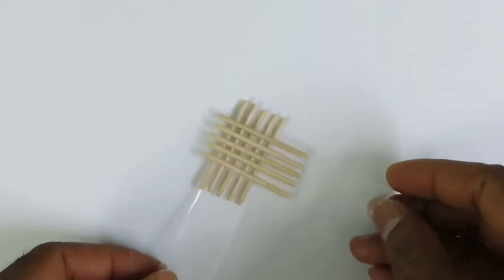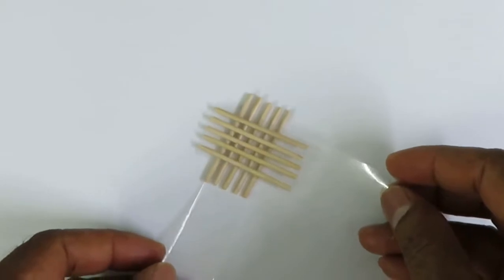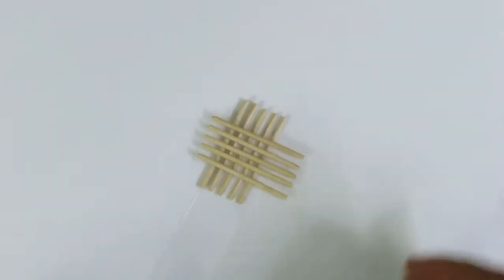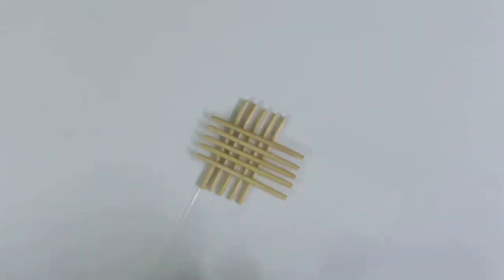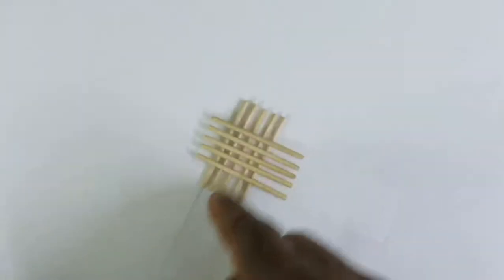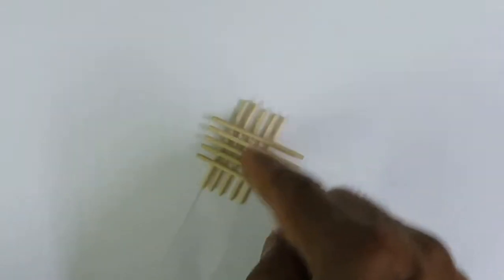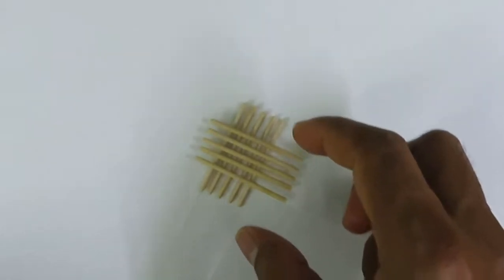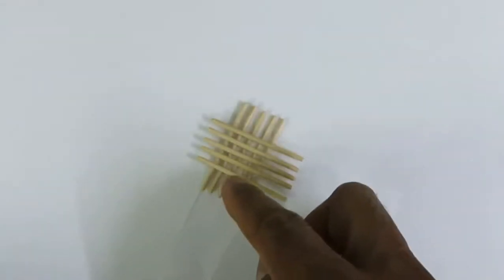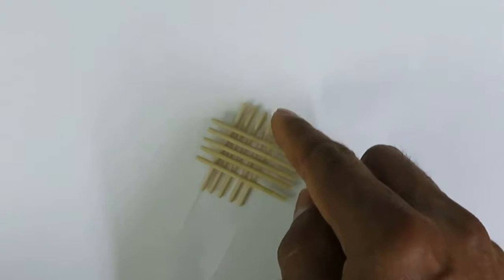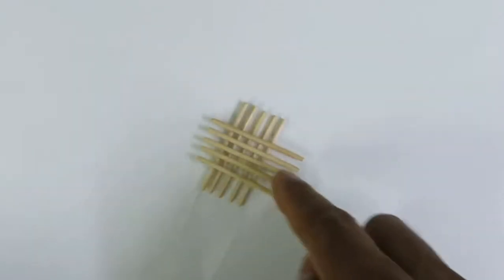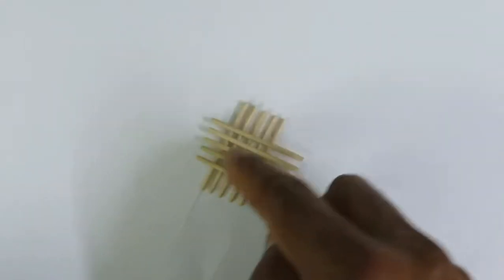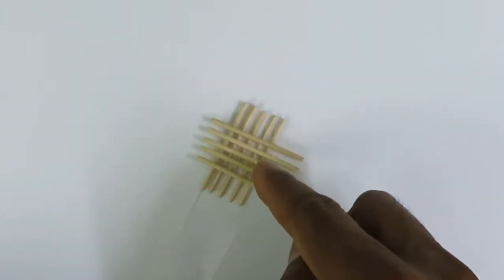Now it also depends how we apply load. For example, if we have this kind of orientation of the layers, and if we apply force, the maximum tensile stress in this direction, then we get the full strength of these fibers, because these fibers are longitudinal in this direction. But these fibers will be transverse because we are applying the stress in this direction. So these fibers may not contribute that much.